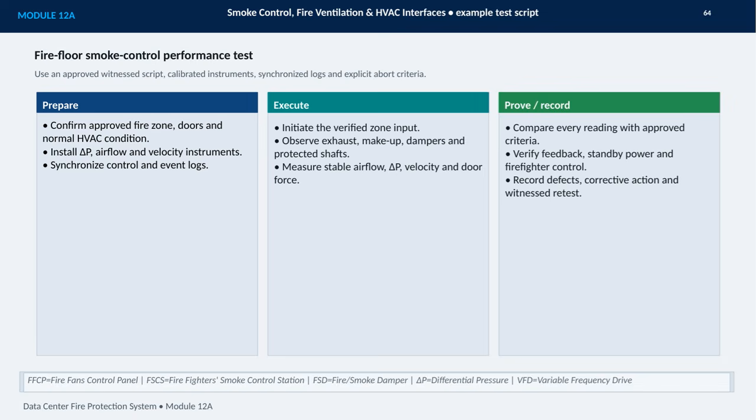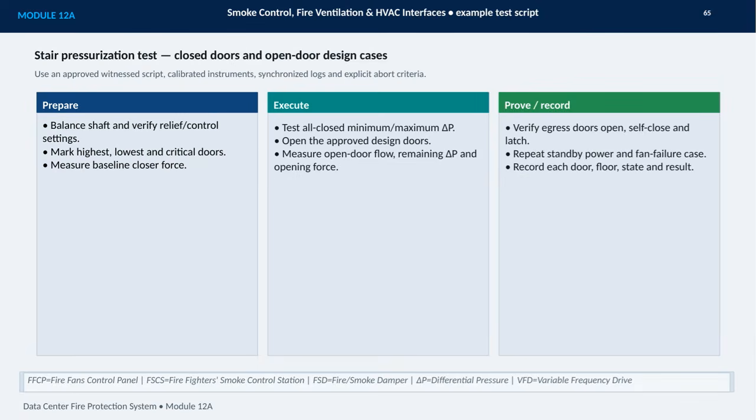I verify system feedback, standby power, and firefighter control through the firefighter's smoke control station. Any defect is recorded with its corrective action, followed by a witnessed retest. This process creates a clear, auditable record from preparation through final acceptance.